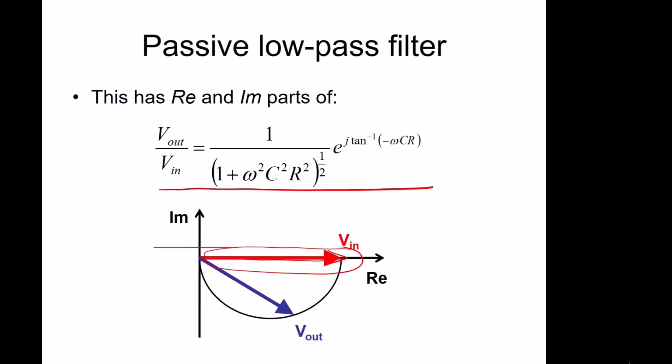As the frequency increases, you start moving along this line, so the output is here. So at higher frequencies, the output is moving this way, so it's getting lower in magnitude, and it's also now getting a phase change on the output. And then at very high frequencies, it'll go to very small magnitude with a 90-degree phase shift here.